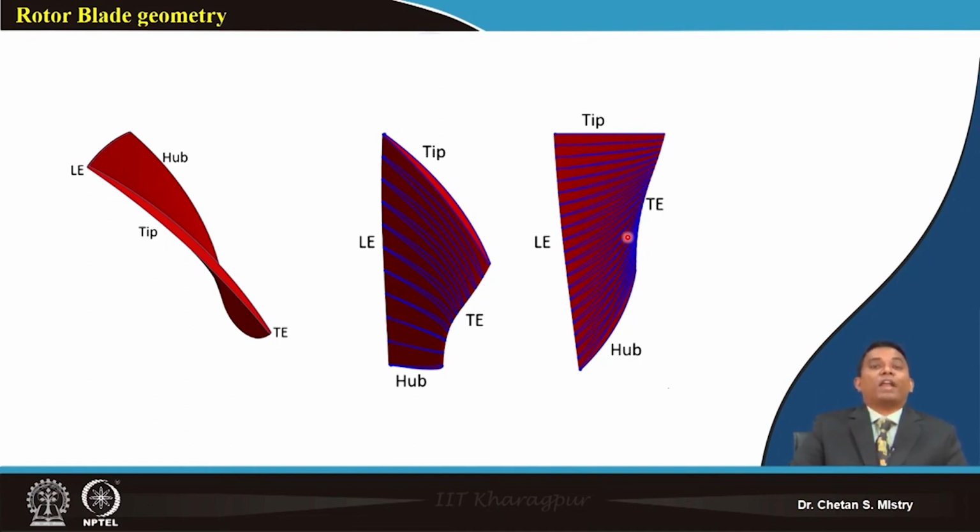This is working fine under design condition. It may be possible that when you are doing your design, it gives best performance, expected pressure rise, even efficiency at the design point. But when you put that under off design condition, suppose 80% mass flow rate or 75% mass flow rate, you will find that it is not giving a wider operating range in the sense of my stall margin. Under that condition, you may need to modify your blades. You may need to modify your aerofoils. If possible, you may need to modify the dimensions of the blade.